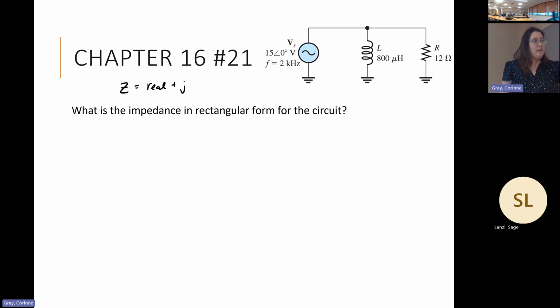parallel RC circuit. With it, we are going to have to find XL to utilize. So just looking at calculating XL here, it's 2 pi times frequency times the inductance value. Will I need to convert in this case? At the end of the day, my XL needs to be in ohms, so I probably should.